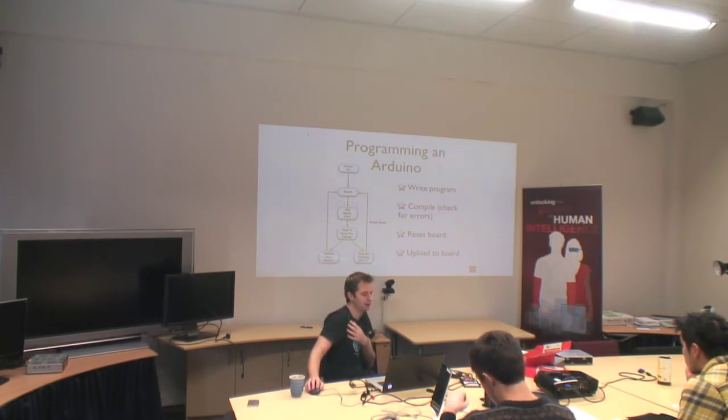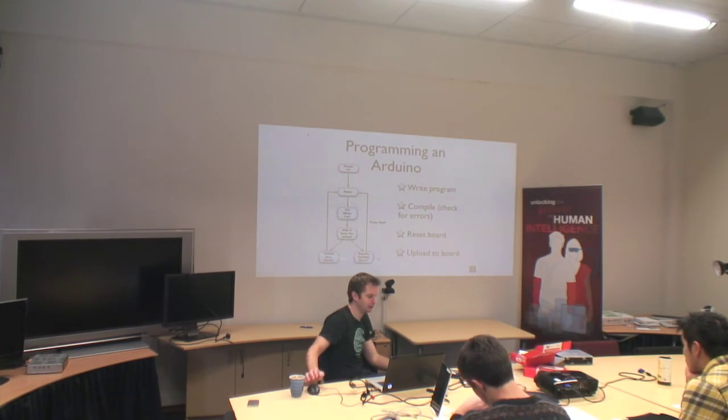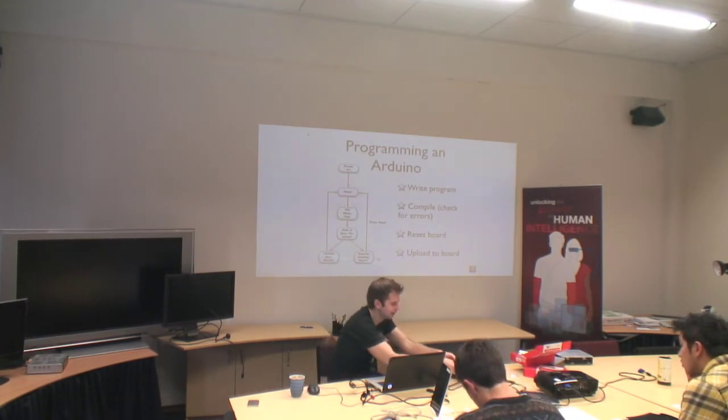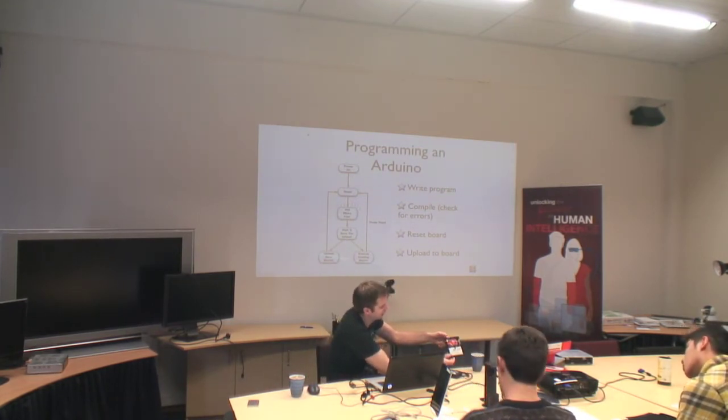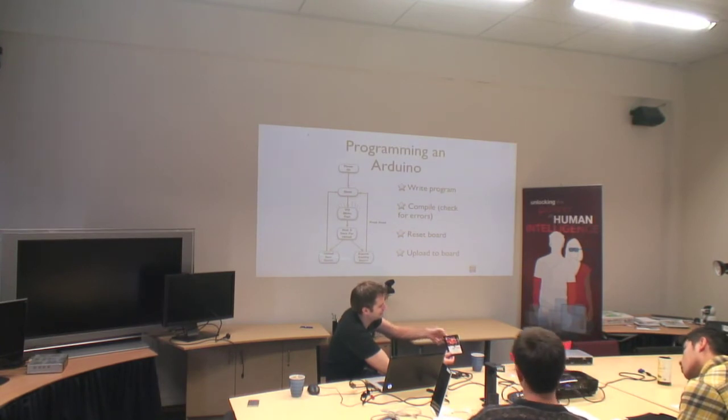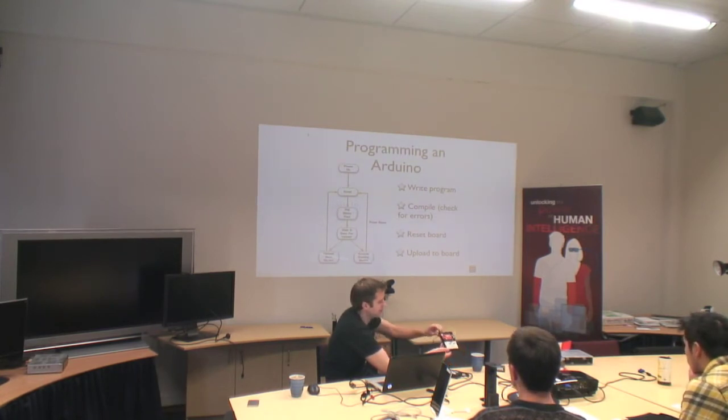So it'll basically start executing your sketch until you push reset, which is this button in the corner here. I push that and it'll just reboot the thing and keep running the same thing. Depending on what your Arduino's doing, sometimes you may want to reset it. So there's a little button here. On this one, it's in the middle there. Usually it's pretty much the only button on the board. We'll just turn it off and turn it on again.